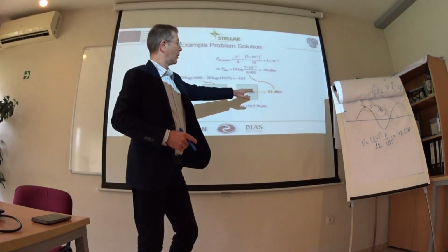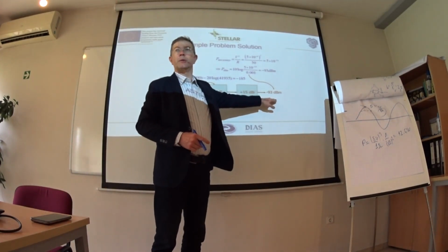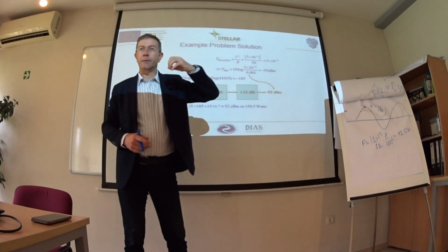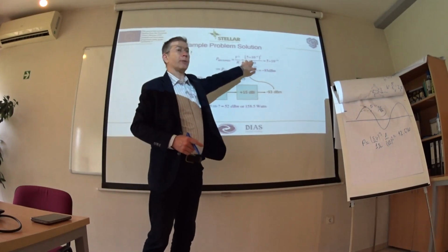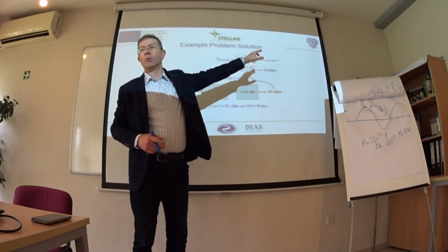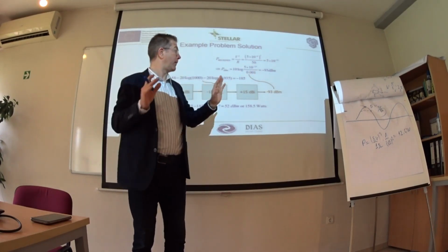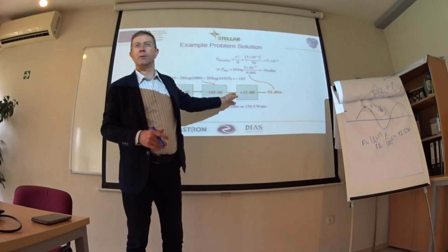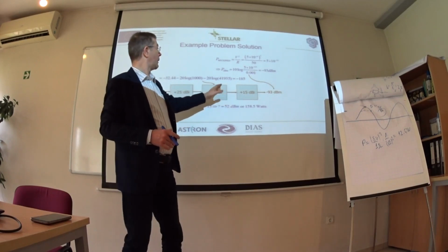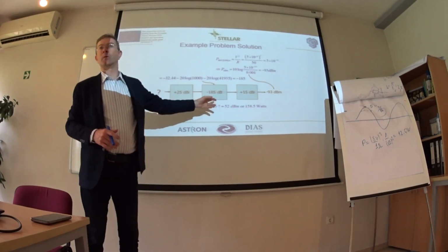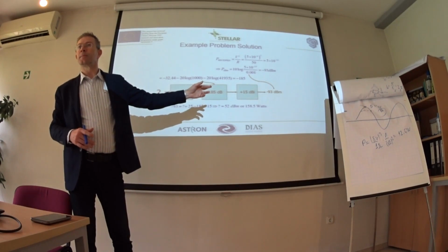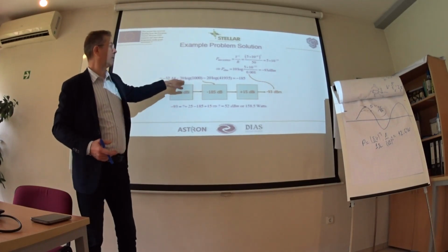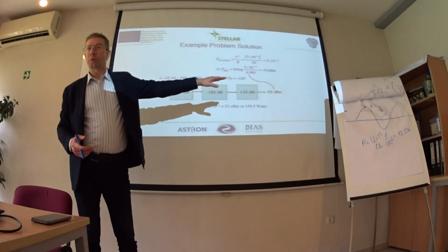Okay, so I guess up to this point everything is clear. We need minus 93 dBm to enter the receiver in order to produce these 5 microvolts. Fine. And then we add the gain of the receive antenna, which is 15 dBi, and then we add this number. What is this number? Loss. Yes, free space path loss, which is calculated by this equation.